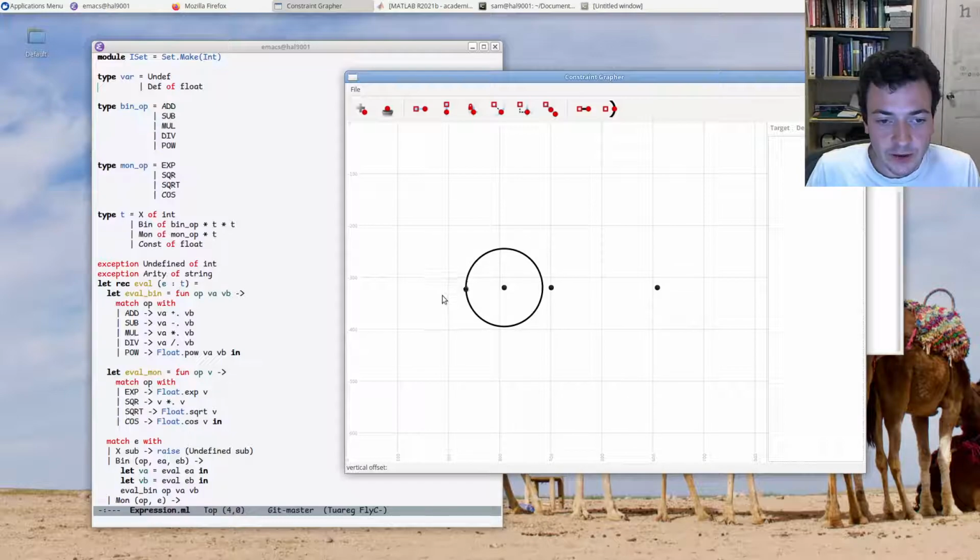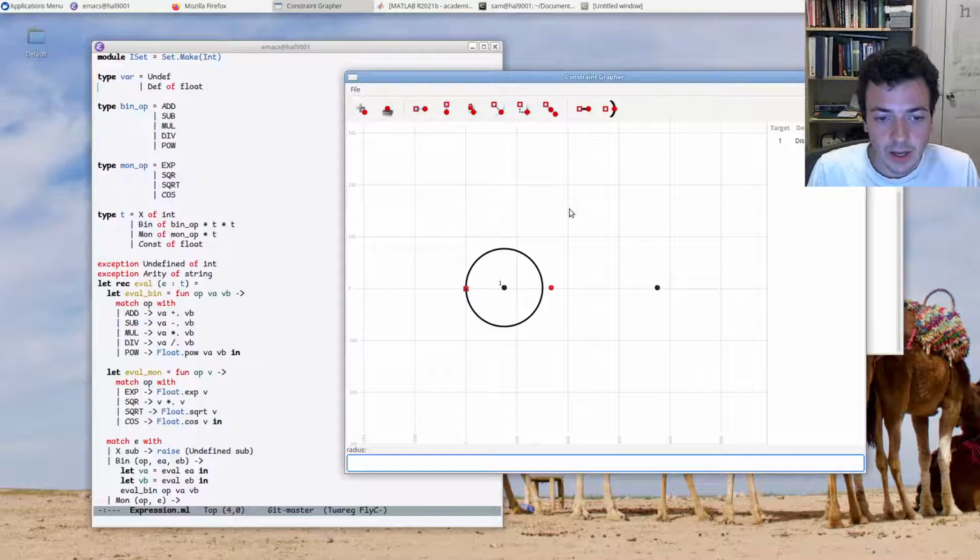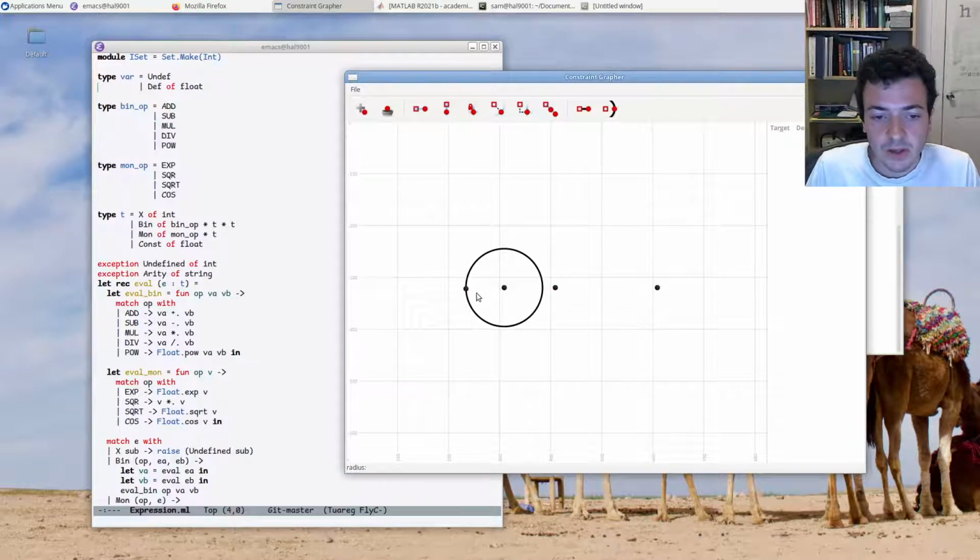And finally, I'll add an arm to attach the wheel to our sliding point with another radial constraint. And we'll say that should be 175, let's say. So to make this clearer, I can ink another line here and a line here. You can see now as I rotate our first point, we have a dynamic system here where the sliding point here adheres to the mechanical constraints that we would expect.